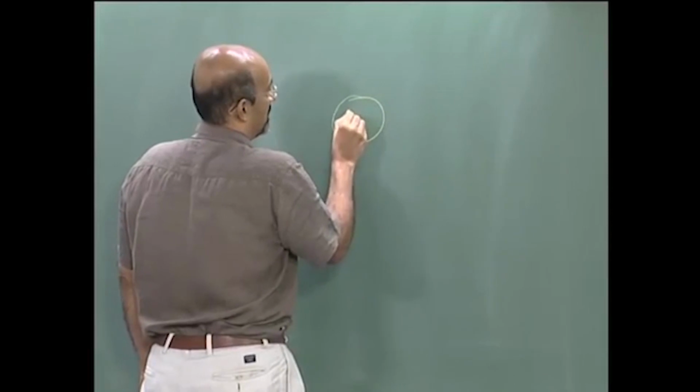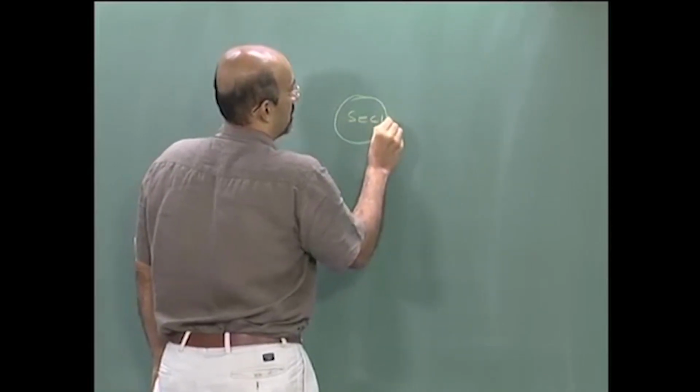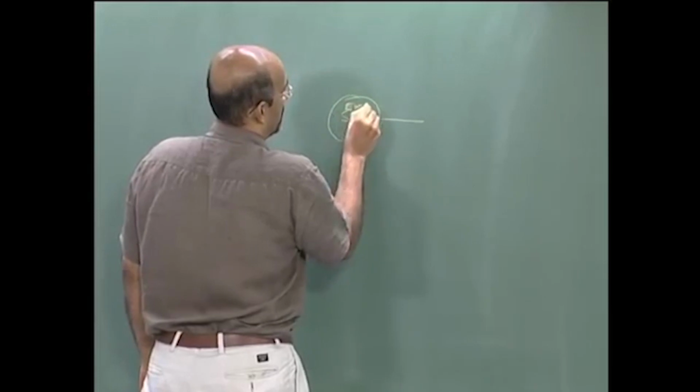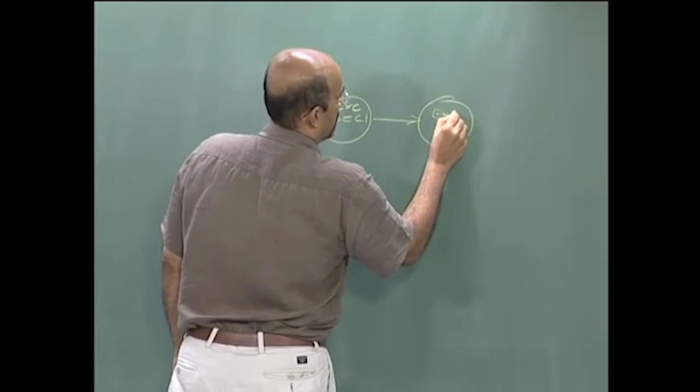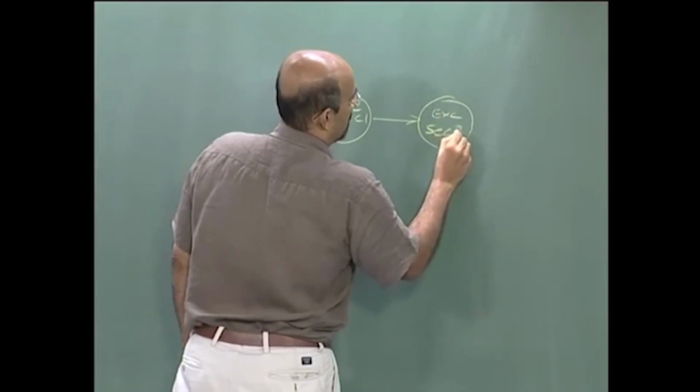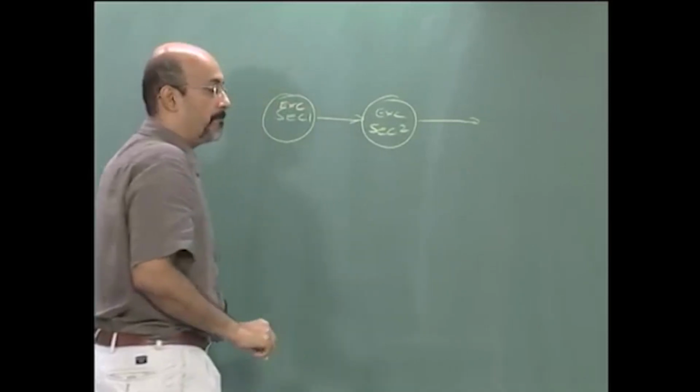So if you wanted to represent this, what are the options? We need to put some delay. You don't have delay in your activity on node, you only have the finish start relationship and you have activity. We can divide the whole pipe into sections, and then we can excavate, lay pipe. You will have excavate, say section 1, excavate section 2, this would go on.